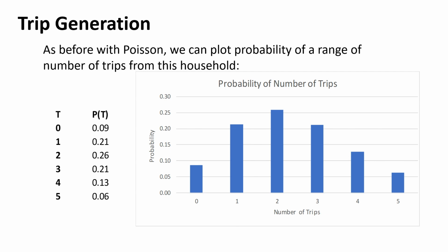It's just an alternative method of figuring out the expected number of trips, our trip generation. It gives you something we didn't have in the other formulation: we wouldn't have known the probability of 3 trips. All we knew is the expected value. Now, using this Poisson, we can figure out the probability that they're going to take 4 trips. And how would we use that?